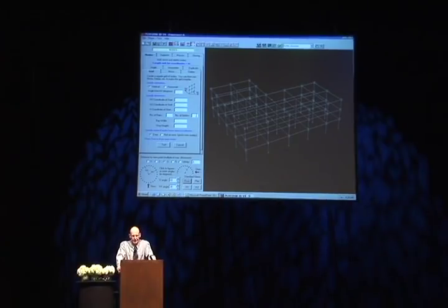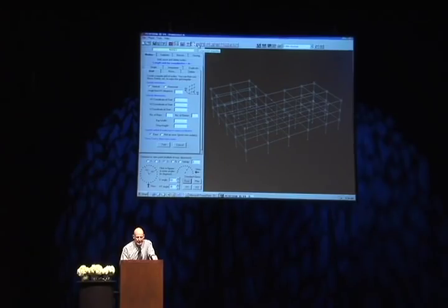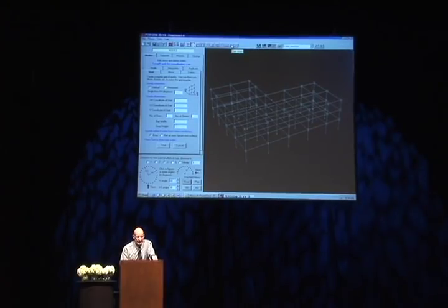You can develop models within Perform quite quickly. You can generate nodes and elements and move them around, all that kind of stuff. It doesn't usually take very long to build a model, even a fairly complicated one. Where you spend most of your time is in this task here, which is component properties, and another task over here, which is limit states.